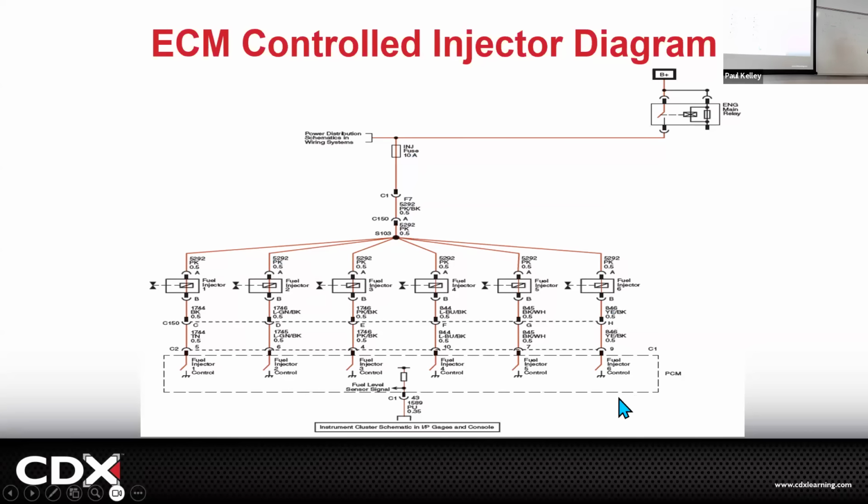The PCM's down here, and you see this little switch? What's the PCM turning on and off? Come on, you got this. Injector's got 12 volts all the time. PCM turns the injector on and off by providing or not providing ground, right? So you'd be like, oh, okay, the injector doesn't work. Does it have 12 volts? I'll test it. Remember, we said 3 was messed up. I'll test it right here at A, 12.6 volts. Okay, this side's good.